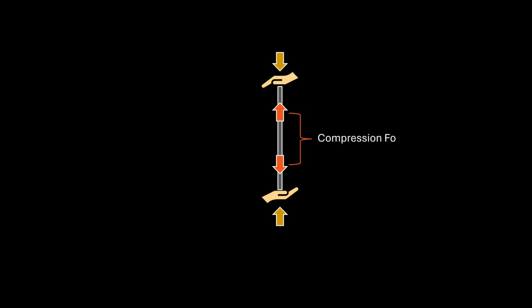If you take a piece of 2x2 wood between your hands and start pushing into the wood, you will experience a concurrent force acting within the wood and pushing outwards on your palms. The force you are applying is a compressive force, and the force that you are experiencing from the wood is the reaction, which is represented by the two arrows pointing outwards. Therefore, compressive force is represented by two opposite arrows pointing outwards along the longitudinal axis of a member.